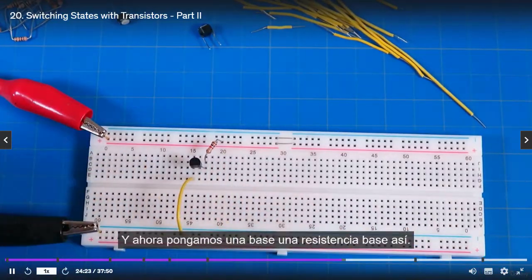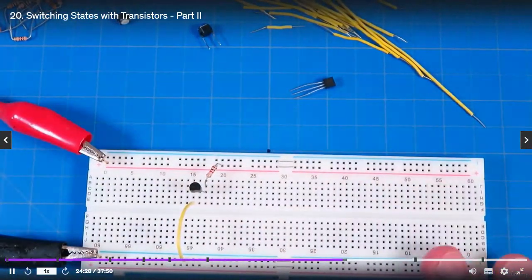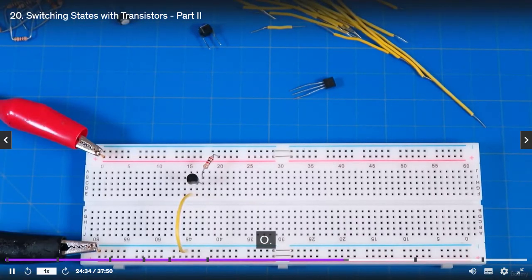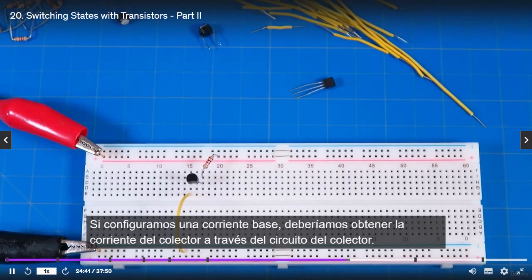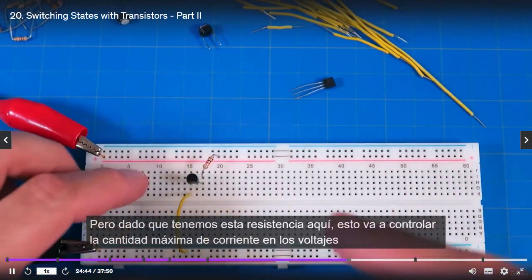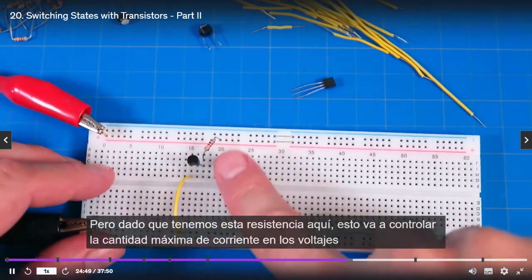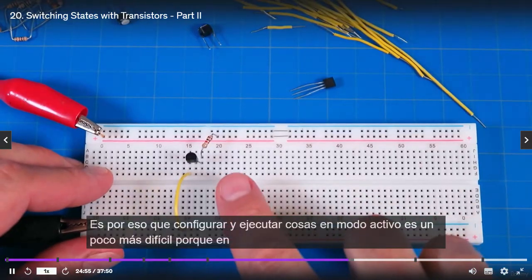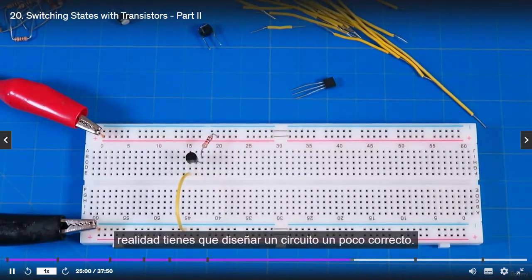Okay, and now let's put a base resistor. So, all right, here's the thing. If we assume that we're going to set it up in the active mode, if we set up a base current, we should get whatever the collector current is through the collector circuit. But since we have this resistor here, this is going to control the maximum amount of current and the voltages that occur inside of the collector emitter circuit. So that's why setting up and running things in active mode is a little bit more difficult, because you actually have to design the circuit a little bit better, right?